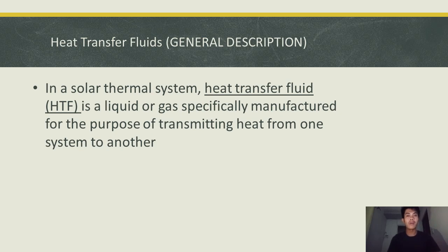HTF, or heat transfer fluids. A heat transfer fluid's operating range is the temperature range between the pumpability point and the recommended maximum bulk fluid operating temperature. The pumpability point is roughly defined as the temperature where a fluid's viscosity reaches 2000 centistokes. At this point, the fluid becomes too viscous for centrifugal pumps to maintain sufficient fluid flow.